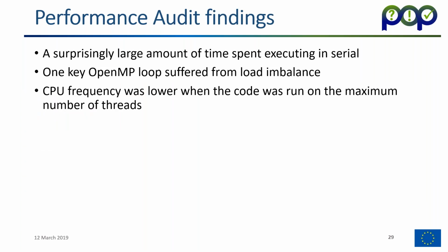So based on these results, we could really conclude 3 things when we looked at zCFD. And these are 3 things that we fed back to Zenotech as things that could be addressed to boost the performance of the code. So we noted that a surprisingly large amount of time was spent executing on a single thread rather than on the multiple parallel threads. We saw one long duration OpenMP loop was suffering from a high level of imbalance. So if we could address that load imbalance, we could get some more performance.